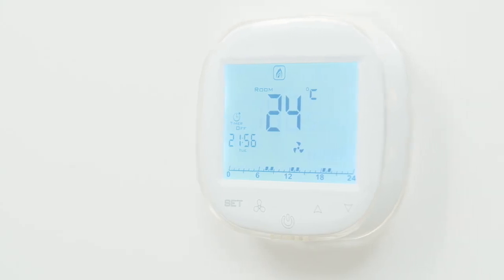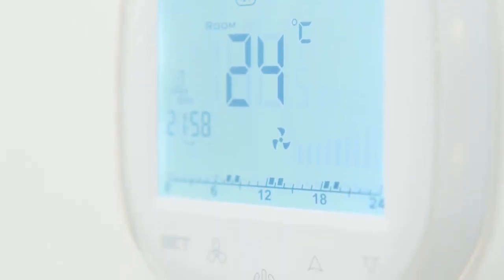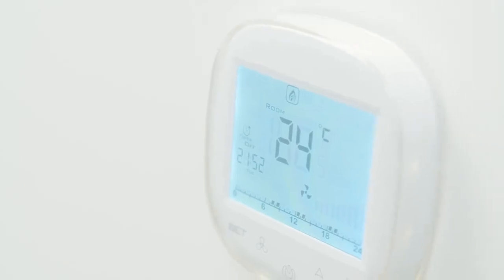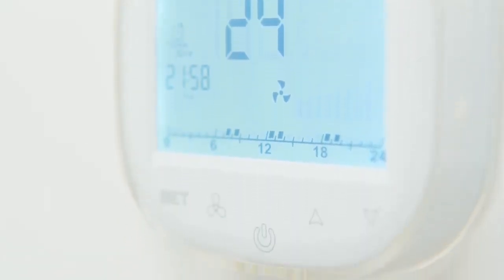The controller is characterized by 3-stage fan speed control with the possibility of assigning specific percentage values for individual speeds, the possibility of programming 4 heating periods for each day of the week, the possibility of connecting a door sensor, cooperation with the building management system BMS, the possibility of connecting up to 8 WING EC curtains to one controller.